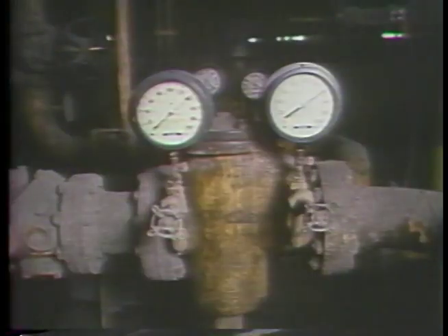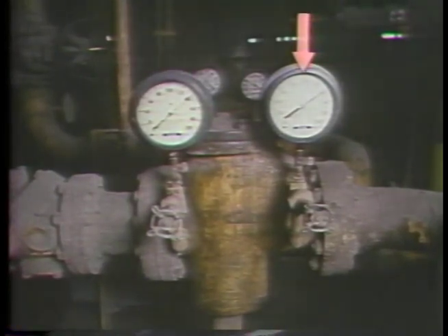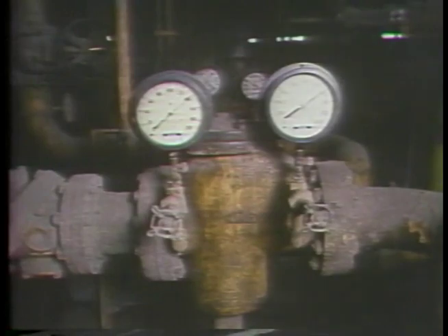One of the most common places where you will see differential pressure used is to measure the pressure across a strainer or filter. As the strainer does its job, trapping particles, differential pressure across it increases. Eventually, at a certain differential pressure, usually indicated in the manufacturer's specifications, flow is restricted to the point that the strainer or filter must be cleaned or changed. It's the differential pressure, or delta P indication, that alerts the operator to the problem.